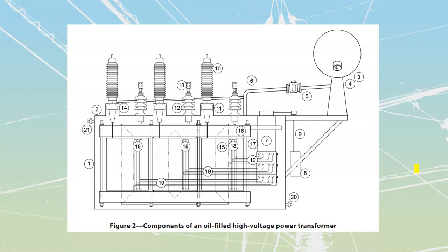If it's a smaller size, we're often going to cool them through air circulation. It's just going to be air that's going to be allowed to go over top of the windings. But the problem with air over top of high voltage windings is that air is often going to have moisture associated with it as well. And air itself is not super dense, so it's not able to always carry it away. Other times we're going to have forced air that we're going to place through fan force. It's going to be thermostatically controlled cooling fans. As it gets hotter inside there, we're going to push more air through.